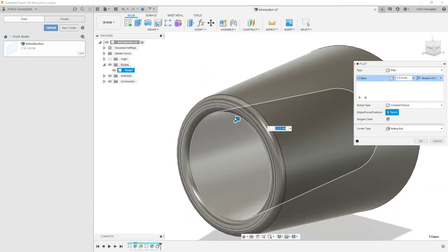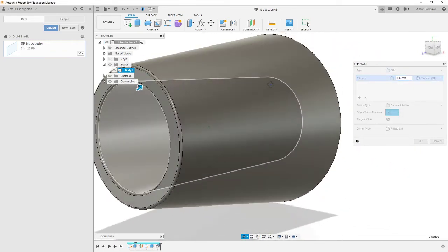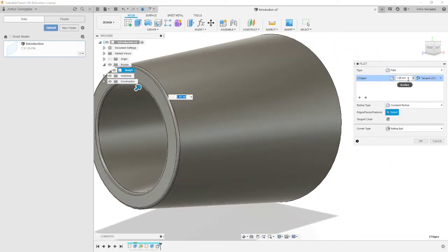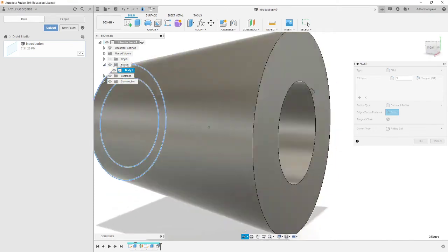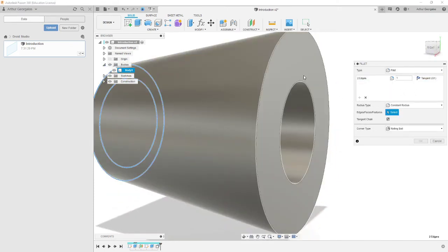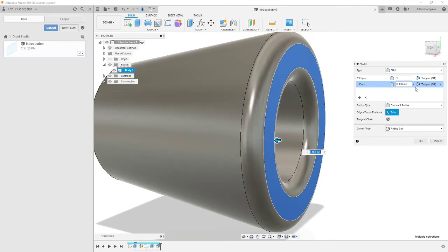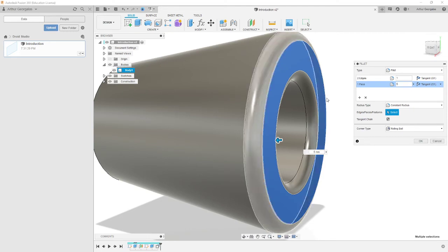I mean, generally we want to do fillets right at the end when we're just dressing stuff up and going for a certain look. And what you can do is just punch in, say we want 1 mil on that, and then we want to do a different kind of fillet. When we go add selection, we can pick this back face, and we can make this 5, right?